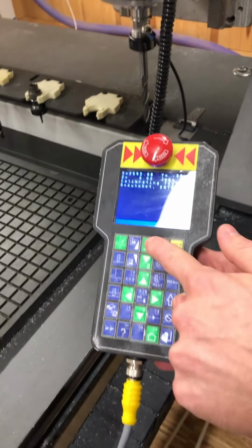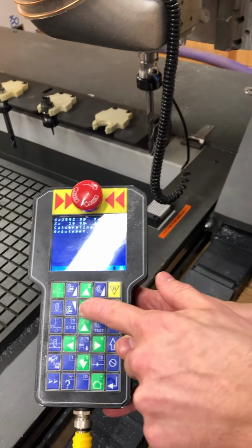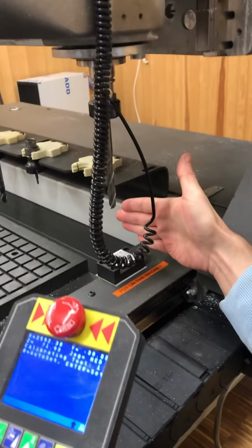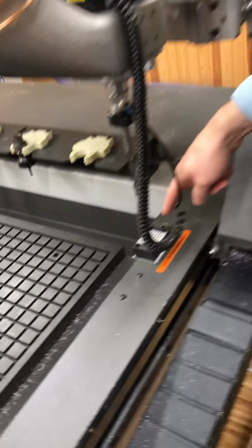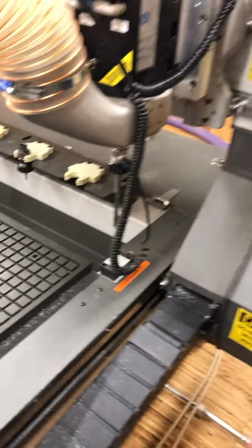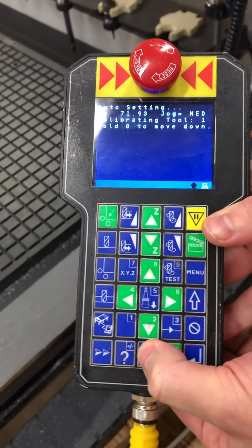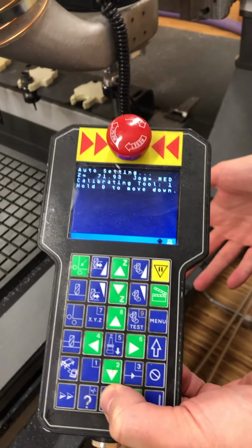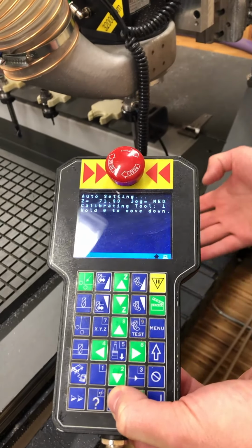And you also jog with the C, with the height here. So you can press C down to go down. But if you have some sort of hand between there, make sure that it's straight above the place here, like it should have been, because it auto moved there. Then you can hold down the 0 key to auto set, and that will go really slowly. Perhaps this was a little exaggerated for safety, but it's good to be safe.